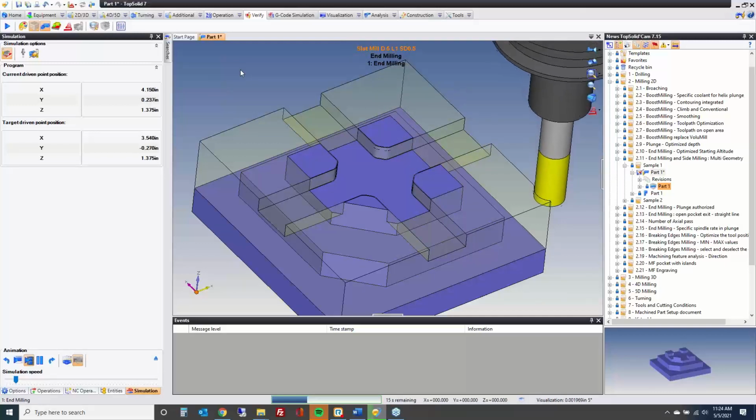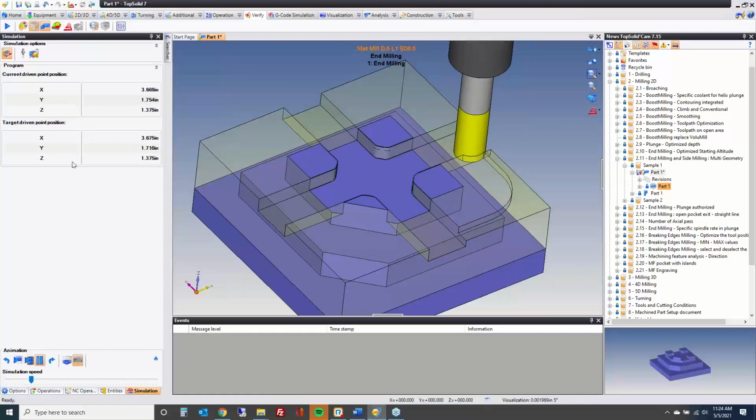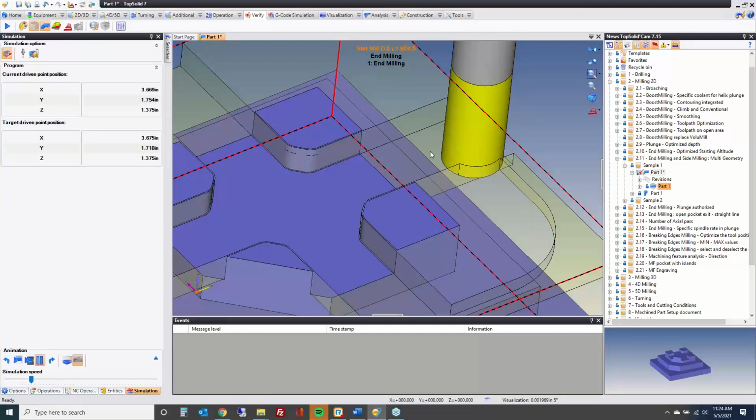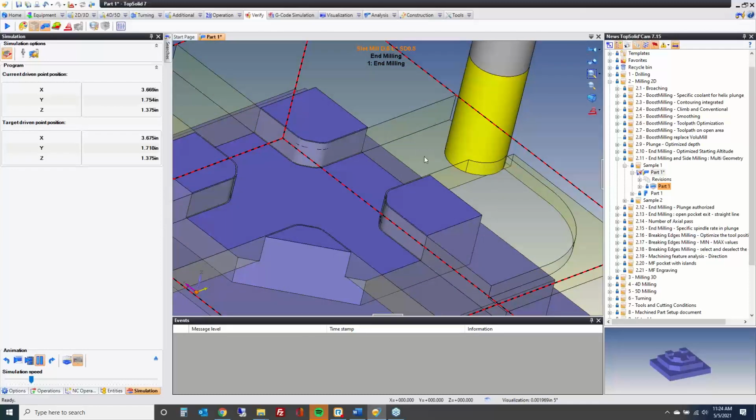And now we're going to nibble. And you notice where it's plunging here? It's plunging in air because it knows the stock is updated there. In 7.14 and earlier, you had to treat these as separate machining operations in order to get that optimized motion. In 7.15 now, we're paying attention to the order that geometry is selected in a given operation to fully optimize that tool path.